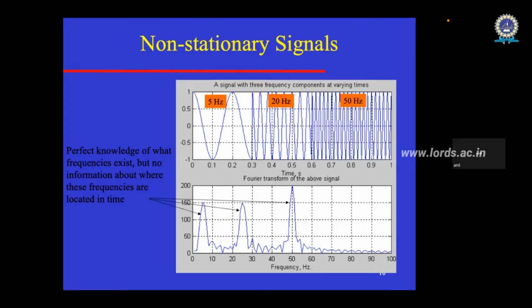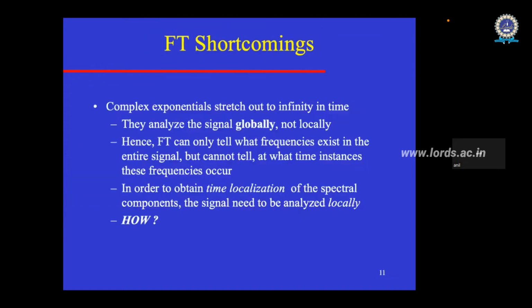This point is very important to understand. Then only can we proceed further, because there are various techniques for time-frequency analysis because of uncertainty. There is not just one perfect time versus frequency representation, because I need some samples to get the frequency, and how many samples, I don't know. If the signal is non-stationary and changing with time, time-frequency analysis has a lot of uncertainty: if I see time well, I can't see frequency well, and if I see frequency well, I can't see time well.